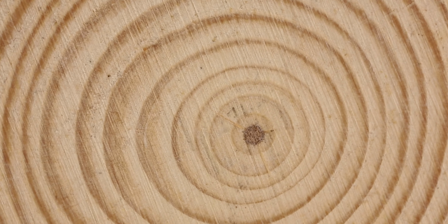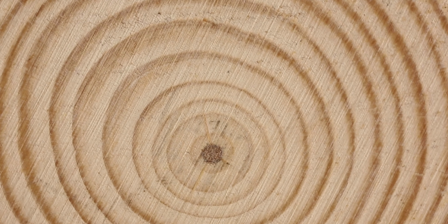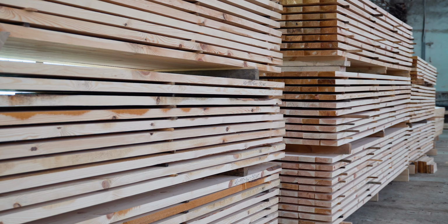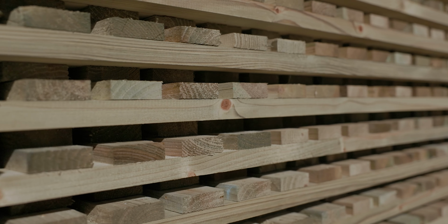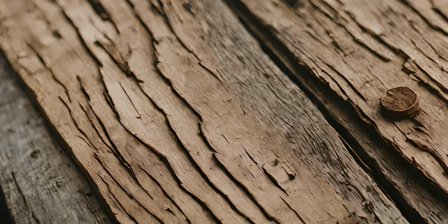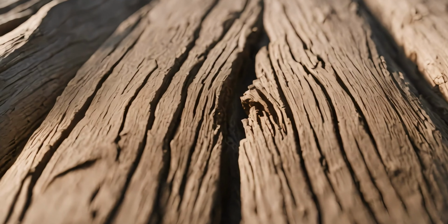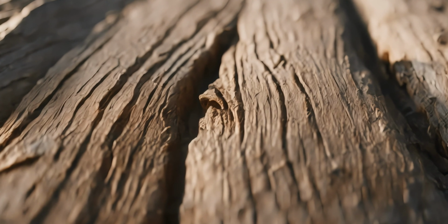After wood is cut for construction, it has to be dried before it can be used for construction. If the wood is dried too quickly at high temperatures, the material can become brittle and cracks form, which completely alters the microstructure. Hence, the method for drying is very important to ensure the microstructure is not altered in a way that compromises the structural integrity of the material when used in construction purposes.